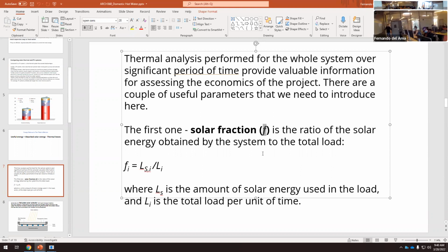If we want to increase the gap of this temperature, if we want to really heat up water to the temperature that we need, probably we need to reduce the water flow. But on the other hand, using the same energy, if we want to keep this difference very low, then we need to increase the amount of fluid. So what do we want?